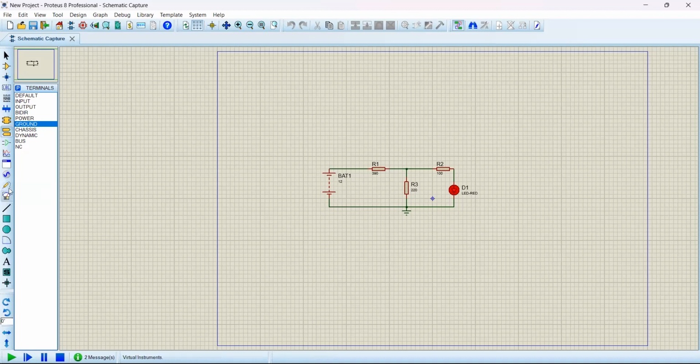How? Let's see how. There's something like a pen there. Underneath that, you can see that yellow symbol. There's a pen and there's a Y. Underneath, there's something that looks like a gauge. The thing that looks like a gauge is the virtual instruments mode. So you click on the virtual instrument modes, then there's an AC voltmeter, DC voltmeter, signal generator, oscilloscope, logic analyzer,